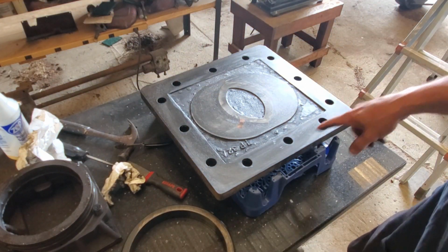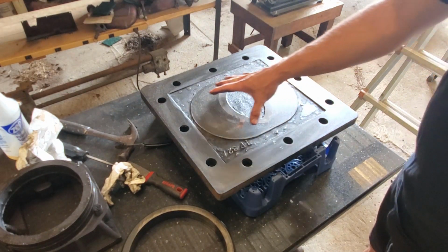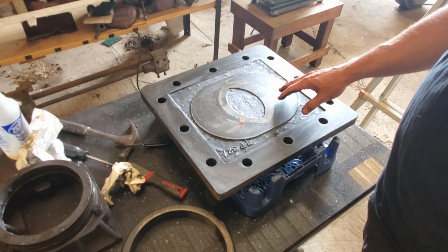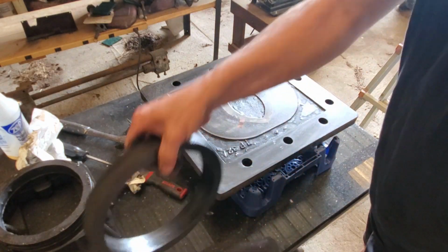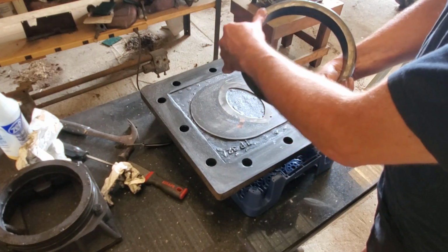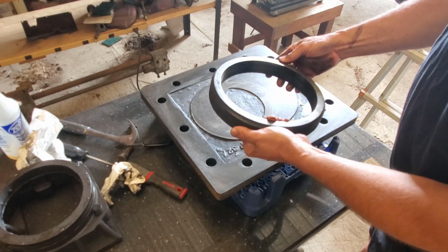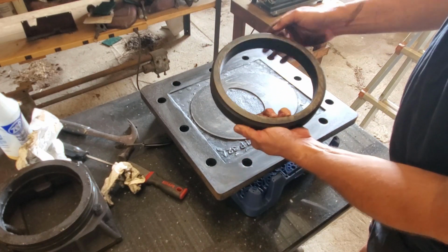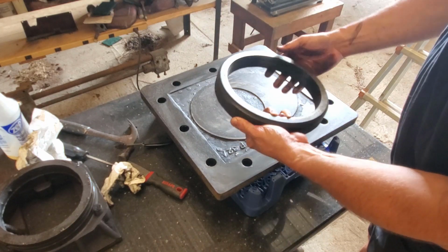So we've got a sealing surface here and then a raised area that represents the approximate travel of the balance piston and unmachined casting there. So the back side of the balance piston, which is this surface, is reciprocating back and forth by the action of the slide valve. And you can see where this thing has definite horizontal scratches in it.